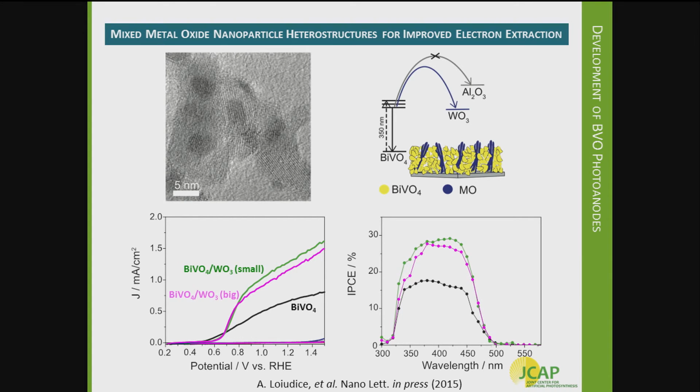Traditionally, if you see that in, say, a pure phase material, it would be that there's a mismatch between the transport length and absorption length. And so you're increasing the width of the depletion region, meaning that you're extracting more and more of those charges out of the thin film. In this particular case, as a heterostructured nanocomposite, I don't want to immediately say that it's exactly the same effect that you're observing because there are additional complexities there. But I would suspect it has something to do with more efficient extraction of carriers by increasing regions of space charge.